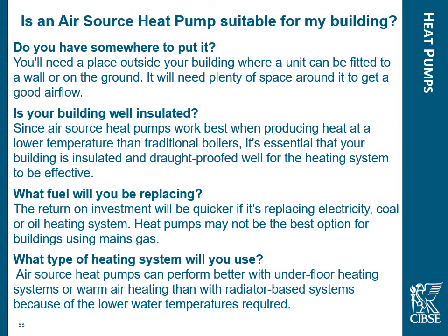What type of heating system will you use? Well, as I've already said, it really ought to be underfloor heating. We could in fact double or treble the size of our radiators and run them at 40 degrees, but nobody really wants radiators everywhere on their walls, etc. So I think underfloor heating will become more and more popular, and I think in the commercial environment underfloor heating works well because it gives us more wall space, and we're not worried about things being stuffed down the back of radiators in public areas and stuff like that, etc.